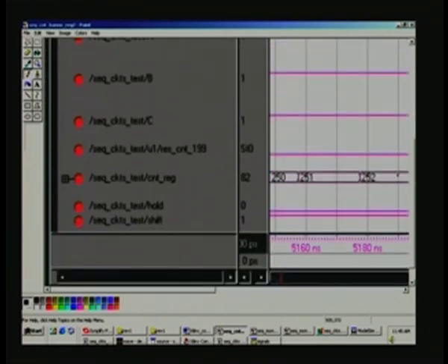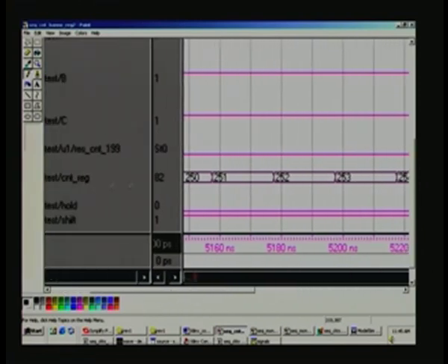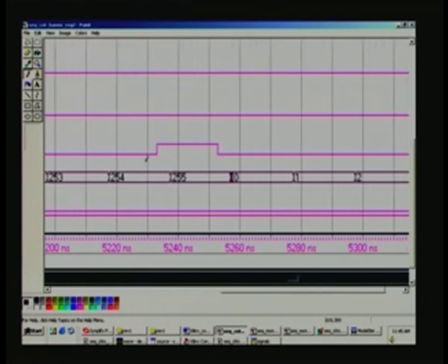So, you can see 250, 251 etc. This is the counter edge here, and you can see that pulse here, and you can see this activity here, some ringing-like thing. In fact, it is changing to 2-3 different values and finally only settling down at 0. That is not a handicap, because this 0 will be sensed only at the positive edge when it is stable. That is what the synchronous circuit is all about.